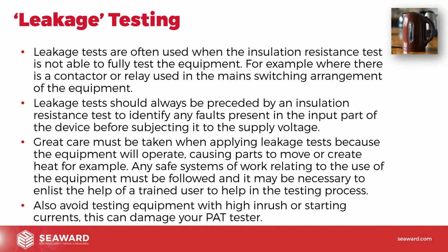So leakage tests are often used when the insulation resistance test is not able to fully test the equipment, for example, where there's a contactor or relay used in the mains switching arrangement of the equipment. A typical example: just imagine something like a computer. To turn a computer on, you press the electronic start button on the front of the computer. That then kicks the power supply into life. The power supply then boots up and starts working, and away you go.